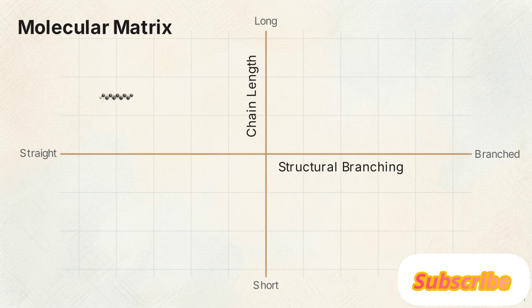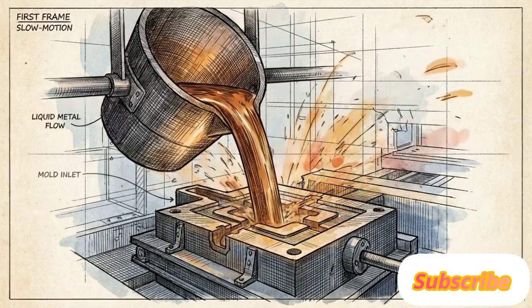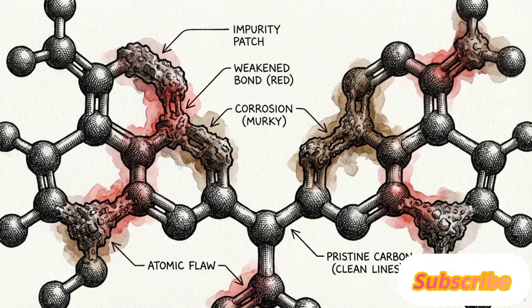Alternatively, isomerization and reforming rearrange existing molecules. They physically snap and reattach carbon bonds without changing the molecule's overall size, moving the paraffin horizontally across our matrix from a straight to a branched chain. The conversion phase functions as a chemical forge, ensuring the refinery's output is engineered for energy density and stability. Even perfectly shaped molecules are flawed if they contain natural contaminants.